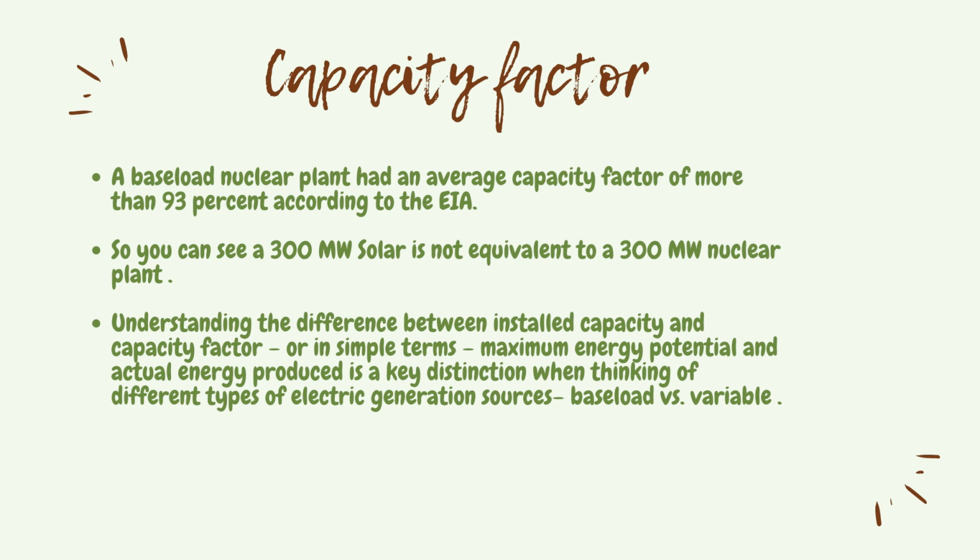By comparison, a baseload nuclear plant has an average capacity factor of up to 94%. So you can see a 300 megawatt solar plant is not equivalent to a 300 megawatt nuclear power plant because of the huge difference in their capacity factors.